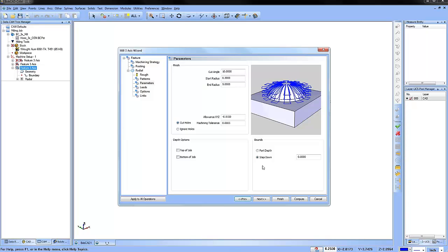In 2D, you have flat geometry, so the step over you get on one side of the part is going to be very close in most scenarios on the other side of the part. But in 3D, depending on the curvature of the surface, the step over is going to give you a different cusp height, because as the surfaces become more vertical, the step over distance doesn't necessarily accommodate for that. Again, that's going to depend on the toolpath that you're using. So that's just a quick answer on that, but hopefully that makes sense.